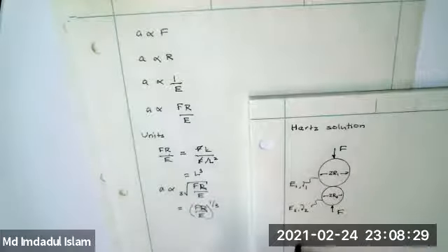then A, according to the Hertz solution, I'll use this cube root, but you're welcome to use the 1/3 power. And now we have a constant of proportionality. It's the cube root of 3/4. The cube root of 3/4 is about 0.9, so it's very nearly a constant of proportionality of 1, but it's not.